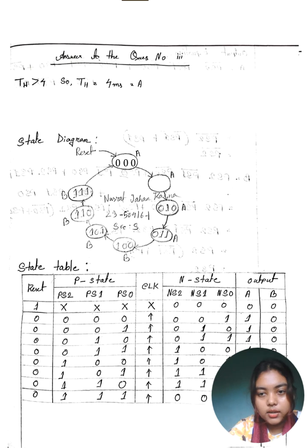Transitions between states are shown by arrows labeled with inputs A or B that cause the transition when the clock edge occurs. The inputs are labeled A and B on the transitions. There is also a reset input that takes the circuit to the 000 state.